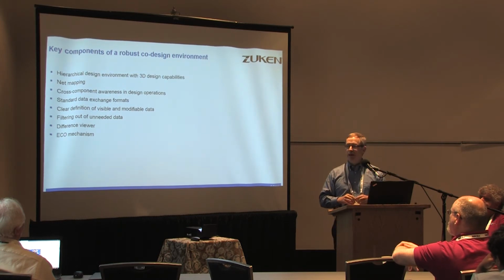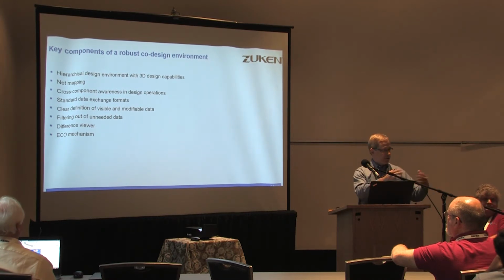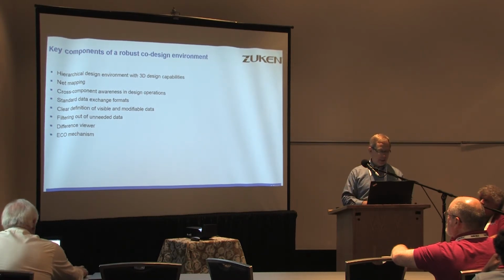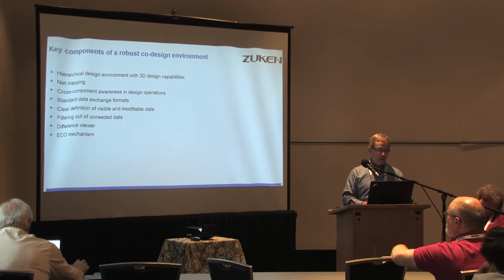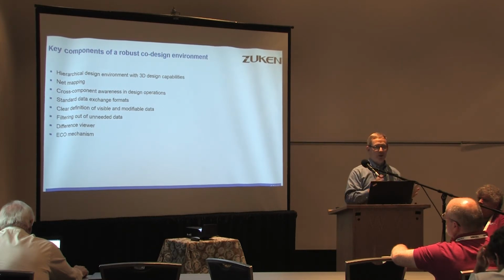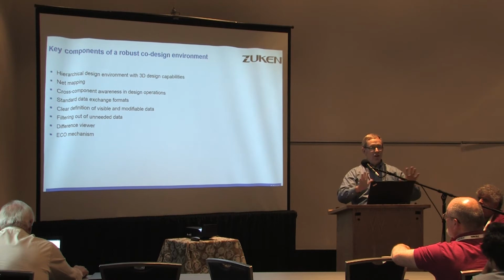Standard design exchange formats. This is one of the places that we talk about in our working group. What formats are needed to be able to bring this data together and share data between the various design tools? And of course, open access is a big part of that. You need a clear definition of what's going to be visible and what's going to be modifiable. Got to filter out unneeded data because there's a lot of stuff out there that you don't need in the core of the die when you're doing chip package board co-design. And you need a difference viewer and ECO mechanisms. So when you have these things in each of the design tools, you'll be able to much easier communicate and collaborate.